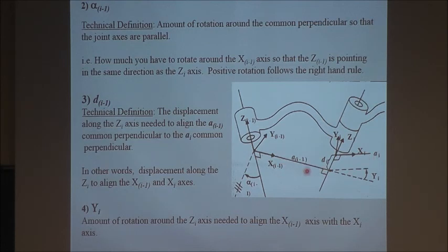Remember that you have a set of DH parameters, 4 for every joint. Every joint has 4 parameters. We are talking about going from i minus 1 to i. But you have to remember that a_i here and x_i are related to a common normal from joint i to i plus 1, somewhere beyond here.